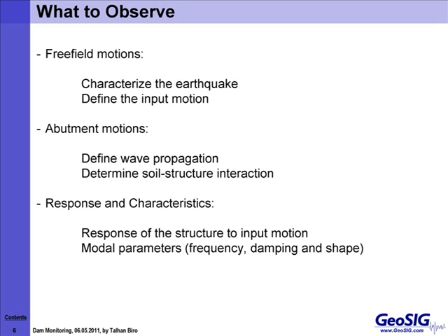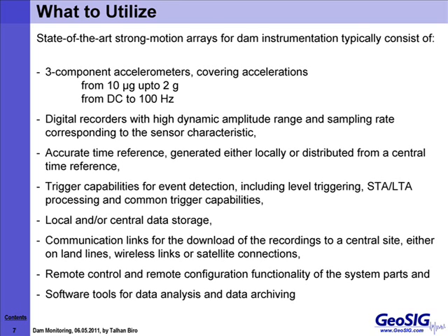We can also define the modal parameters, which are the modal frequency, the modal damping, and the modal shape, which we have seen, I think, one slide before, so that we can understand how our dam is behaving under the input motion. To be able to observe all this, we need to utilize strong motion instrumentation.